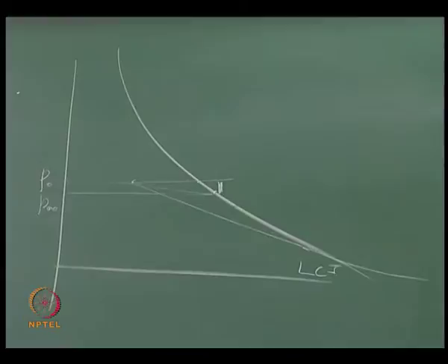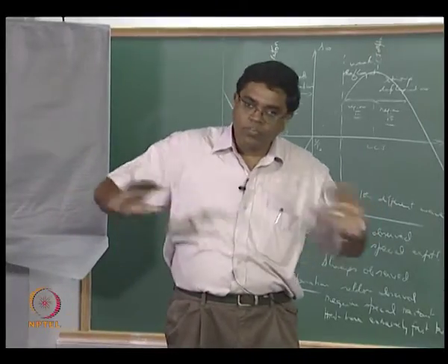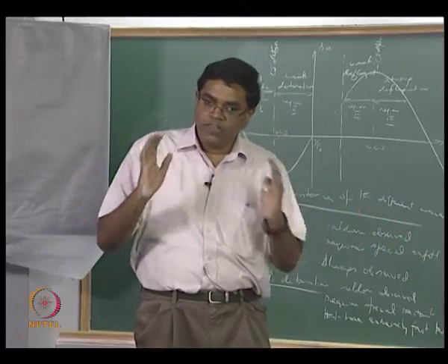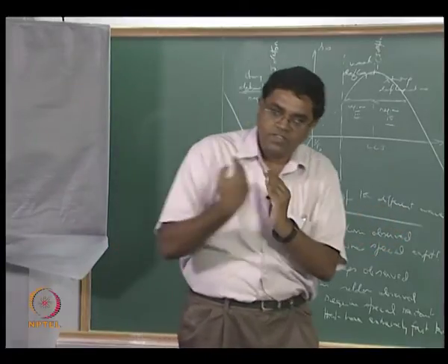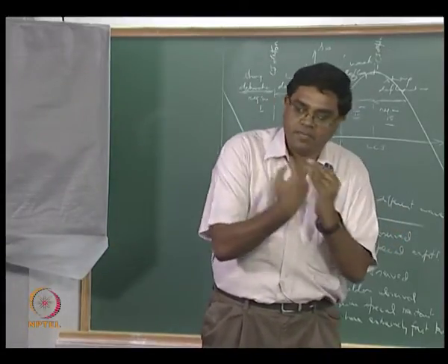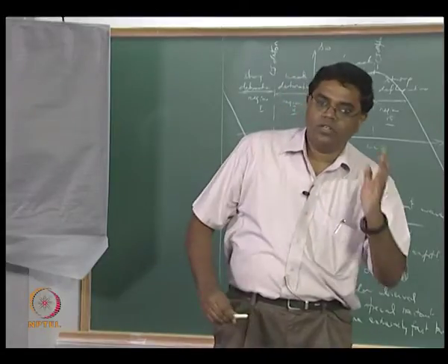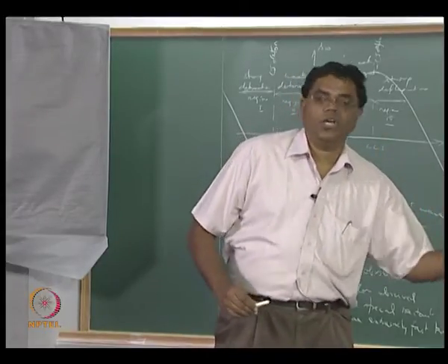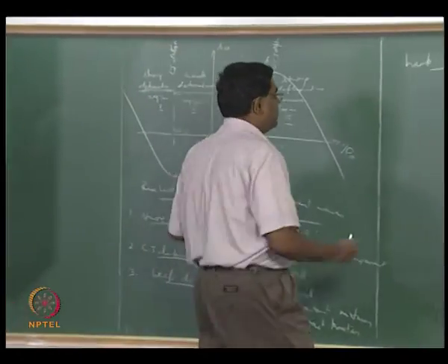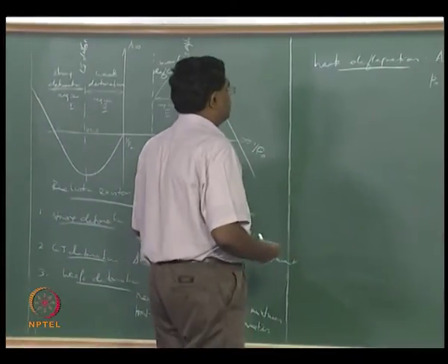You are typically talking about open systems, and in open systems you have almost a constant pressure process. It is only very close to the flame that it is possible to have this acceleration and this expansion, therefore the pressure decreases a little bit, not a whole lot, and that is exactly what gives you a weak deflagration.